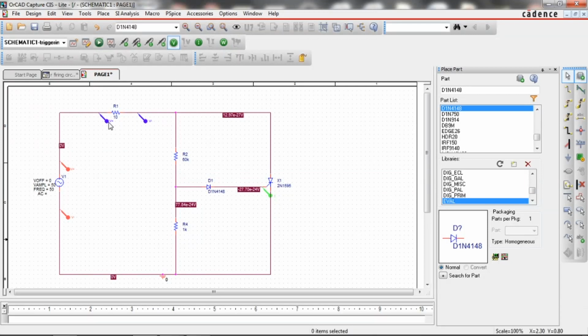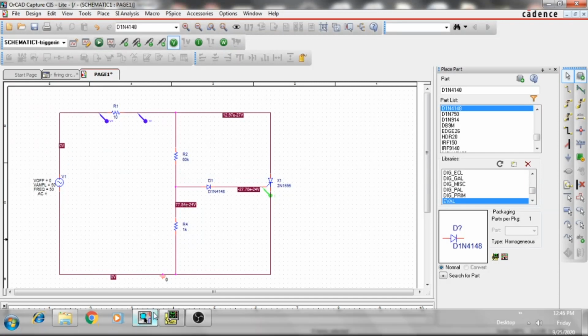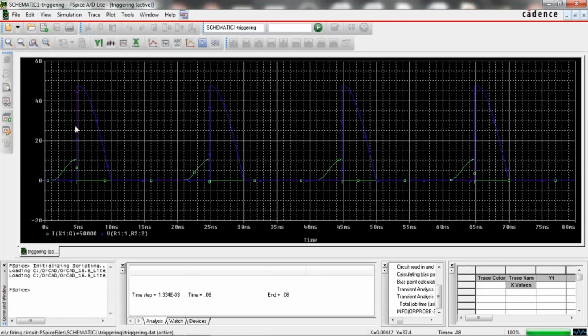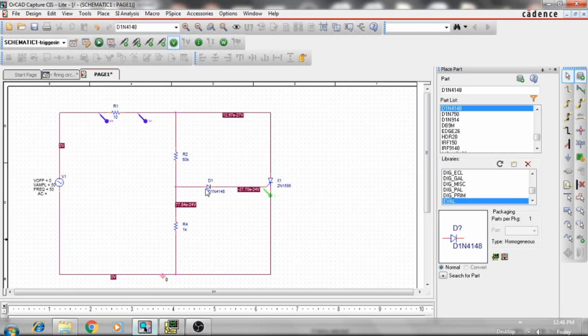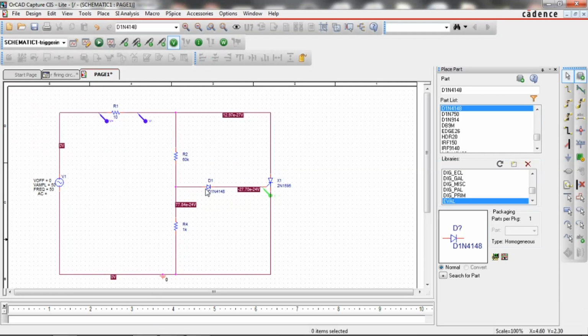So I think input, no need to see. This is our output voltage. This is our current pulse. As soon as the current pulse reaches that required value, which is enough to turn on the SCR, the thyristor will turn on, so load current starts flowing, so load voltage will be observed here from that point onwards till the end of the half cycle. Yes. So one problem we have solved here, and there is one more problem.